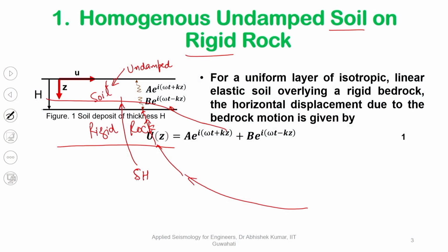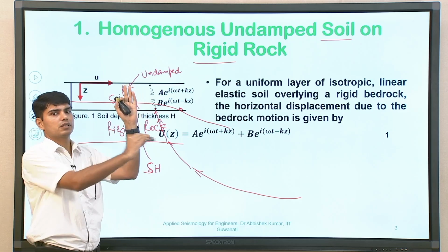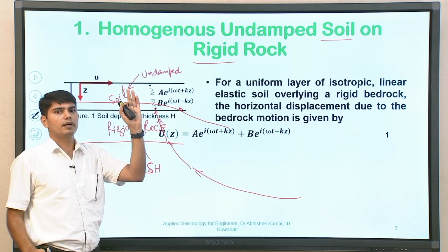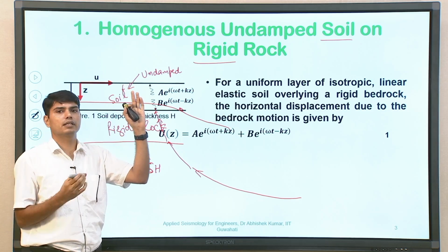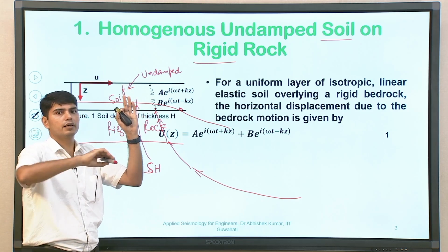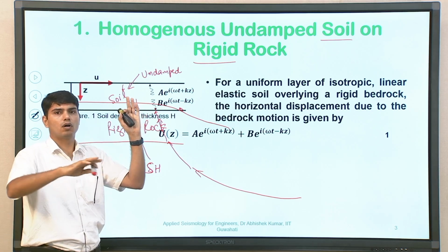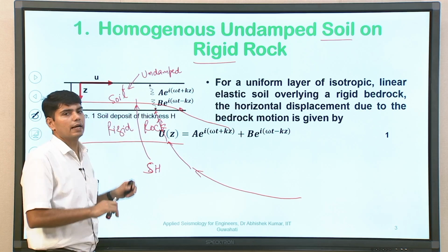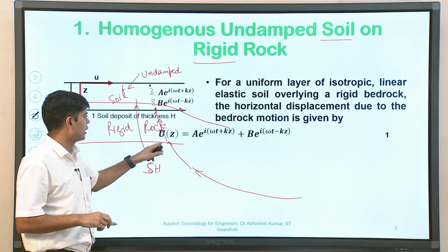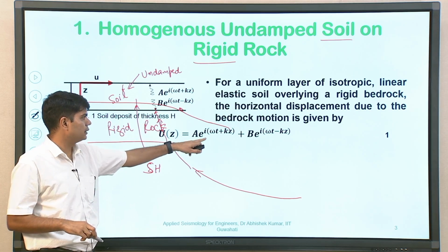So, this is a vertically propagating SH wave, which is going to induce shearing in the horizontal direction in both directions. So, if the wave is propagating like this, shearing will be happening in this direction as well as in this direction, and this is the stratification in the soil layer. And in our ground response analysis, there is an assumption that the soil layer is extending infinitely and is horizontal. So, with that information in the background, u is defined as